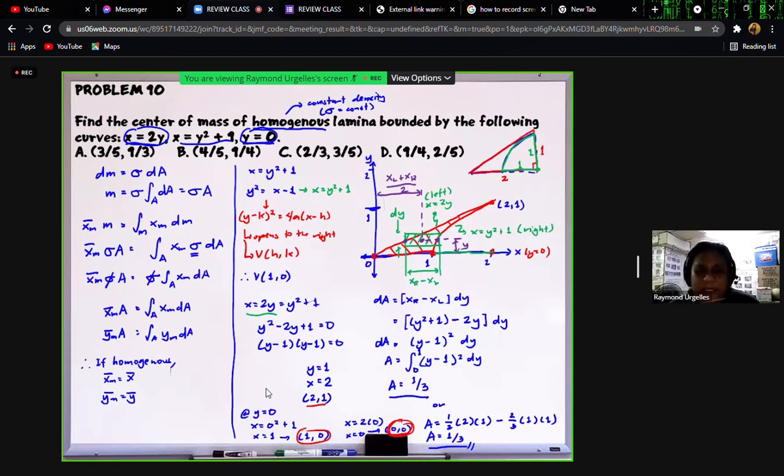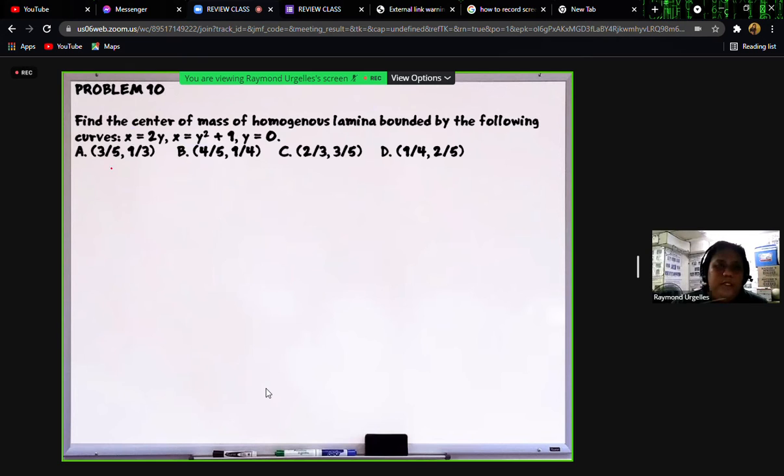Okay. Now let's calculate the centroid, because the center of mass is the same as the centroid for this problem. Let's start with the x-coordinate of the centroid. For the x-coordinate, this is what we will use inside the integral. Again, our equation is x bar times the area equals the integral over the area of x sub c times the differential area.